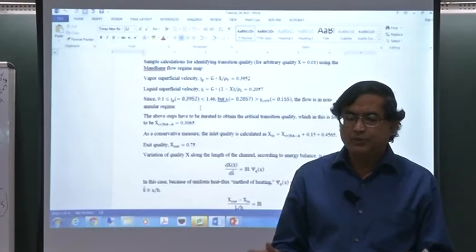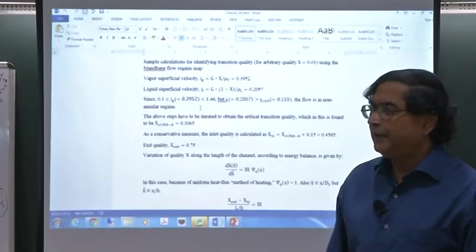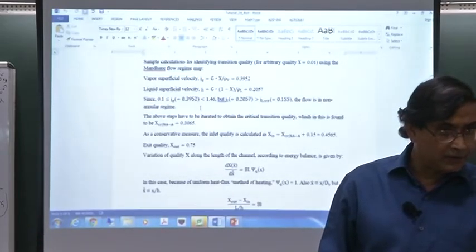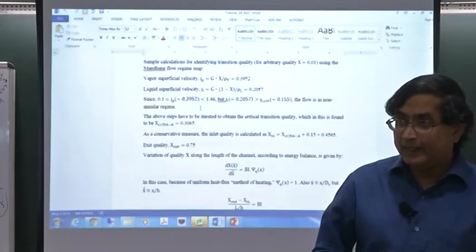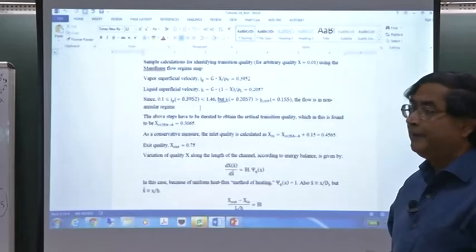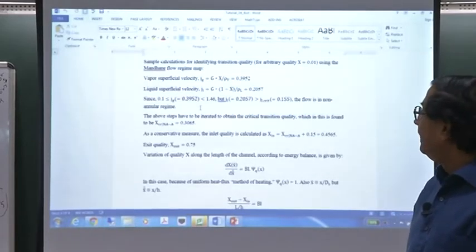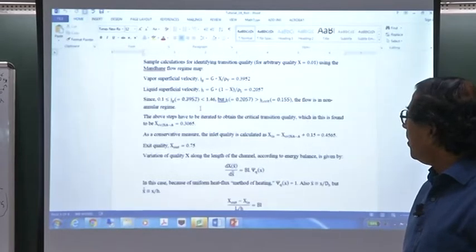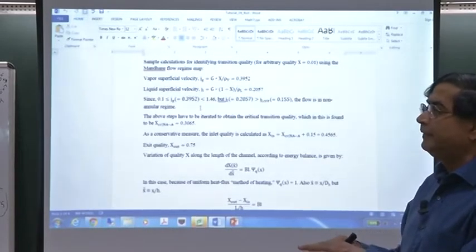So we're looking at these two or three correlations. I am confident that if I come in at more than 0.3 under these conditions, I will be okay at the inlet as an annular flow. You can also find out what the film thickness is, but I'll discuss that after a while. Because you also want the liquid when it comes out of the splitter plate.